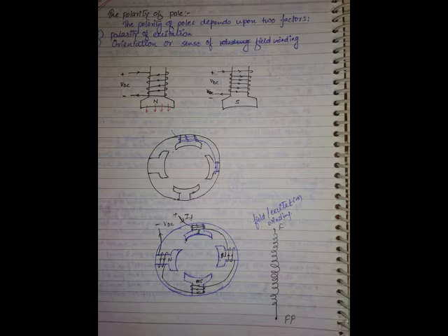As the cross-sectional area increases, automatically resistance will decrease. Resistance is reducing means conductivity is more, so conductivity to eddy currents is more. For example, if you go on a road, the road is very wide and empty, how will you move without any direction? You will be encouraged to move like this. In a similar manner, a wide cross-sectional area means there will be large eddy currents.